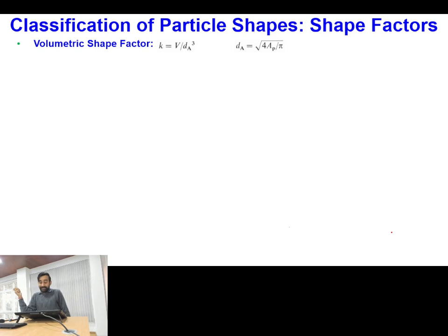So once these are interacting with the surrounding phase, whether liquid or gas, as I told you, we will be having some relation for drag force, some relation for lift force, etc., which will give me the interaction forces. Now typically, if I have to theoretically derive these correlations, theoretically these relations are easily available for spherical shapes. Okay, but not for the irregular shapes.